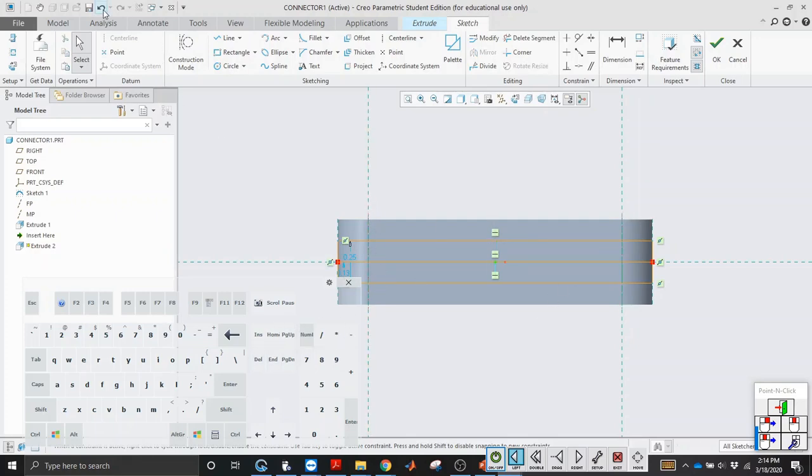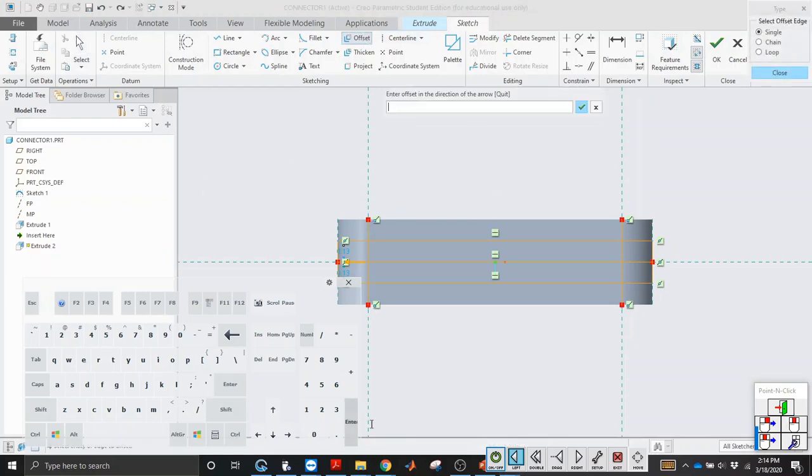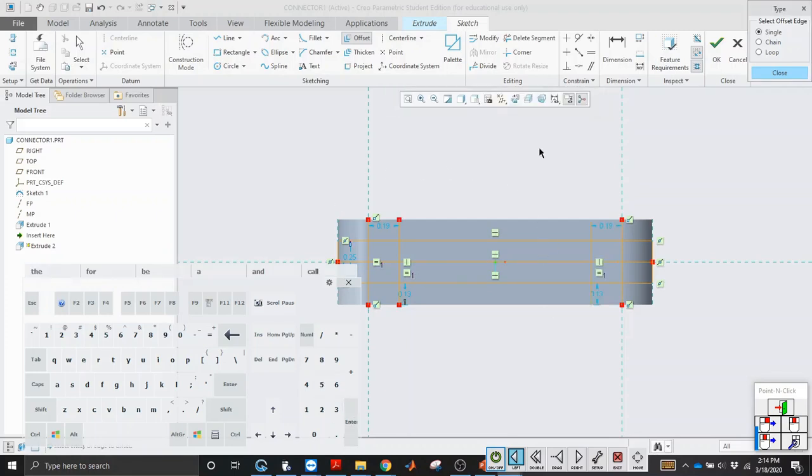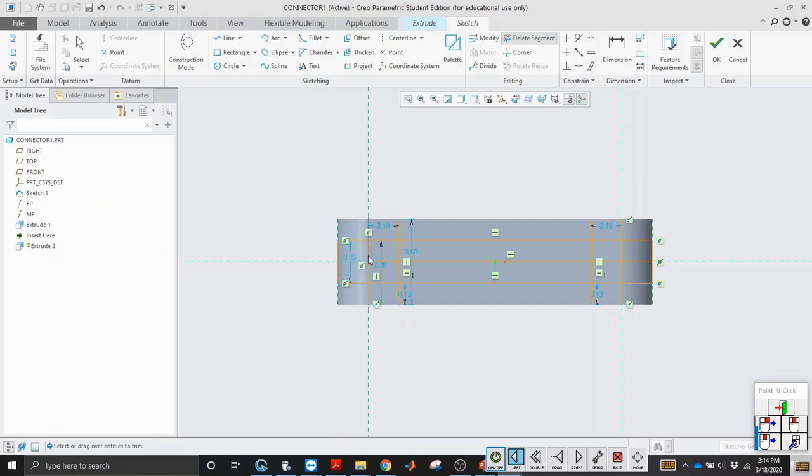So, actually, if the whole part's 0.375, we need to offset. In order for the other part to be able to rotate freely in it, we need to do half of 3/8, so 3/16, which is 0.1875. Same with this, 0.1875. All right, so now we can start trimming. We know this line is not going to need to be here anymore. Or these, we don't need this middle stuff. So we're just essentially getting a slot for our coupler to freely rotate in.